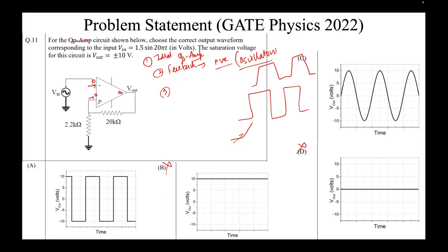Right, so what will we do now? We'll try to find out the expressions. Okay, so this is the V out terminal that we have here. Since this is a virtual short, the value here would be V in. So applying Ohm's law across this 20 kilo ohm resistor, V out minus V in equal to, let's assume the current here is I, and the same current, since no current can go here, will flow here. So V out minus V in equals 20k times I.